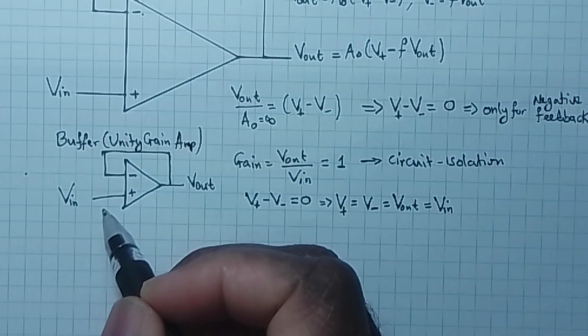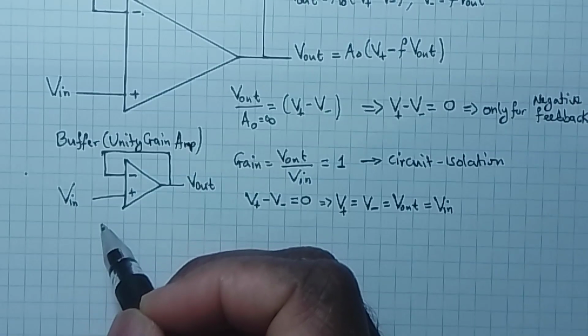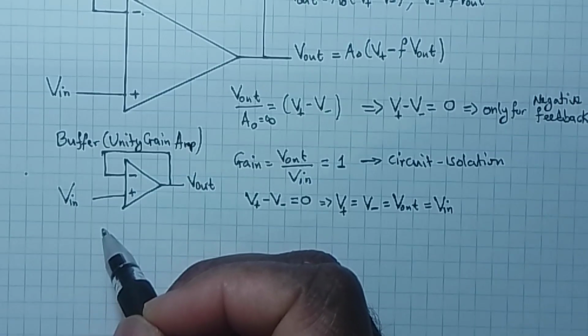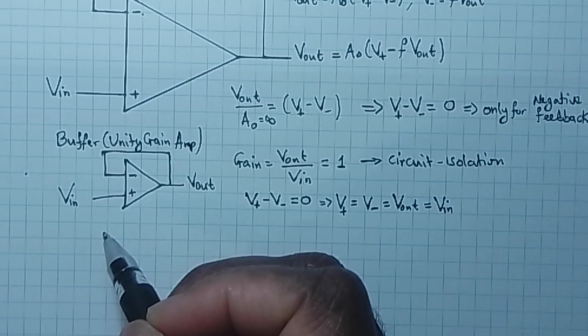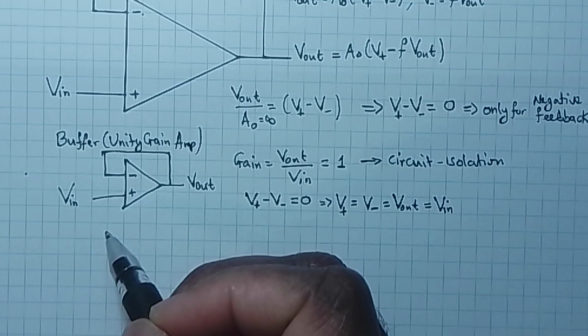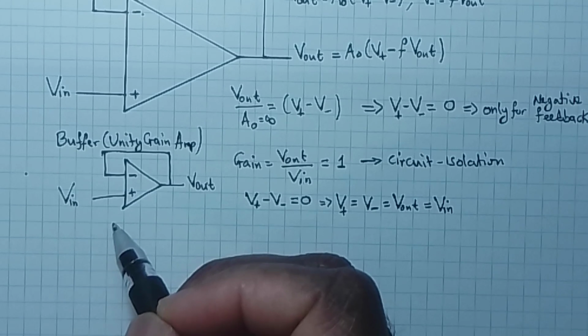But with rare op amps, it may be necessary to throw in a resistor in the feedback loop. The resistor then reacts to minimize voltage offset errors caused by input bias current or leakage.